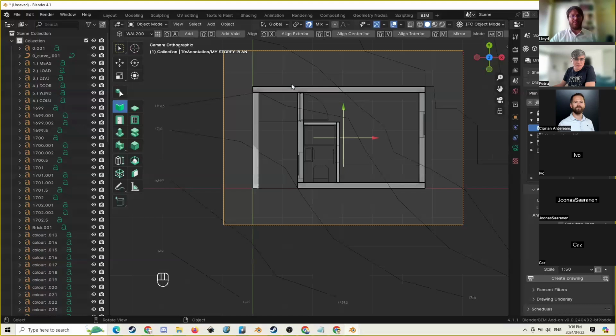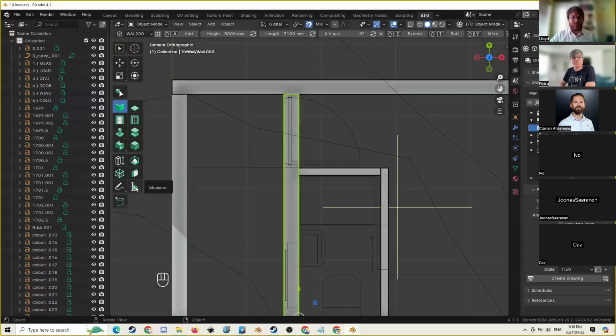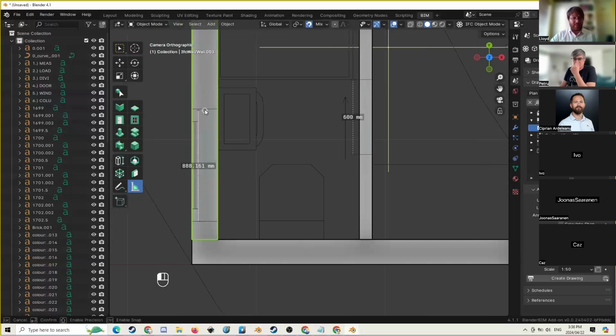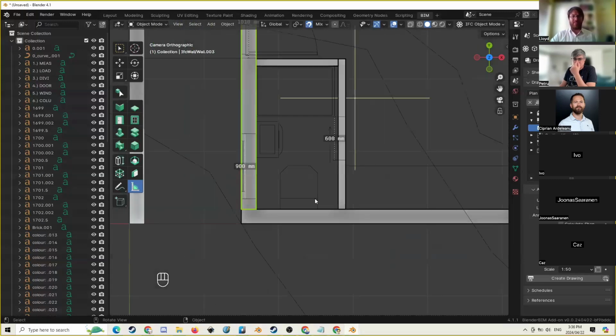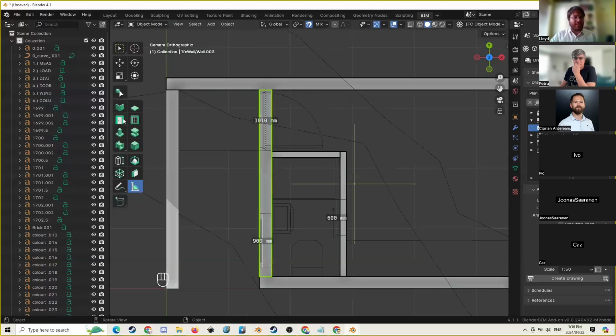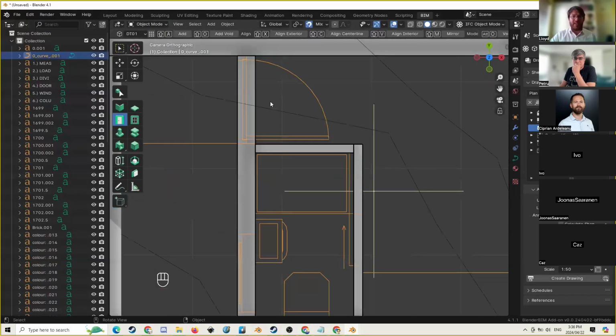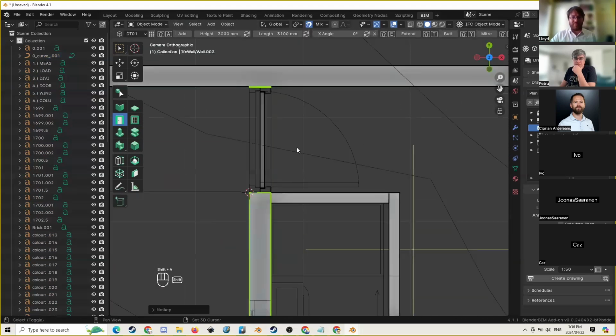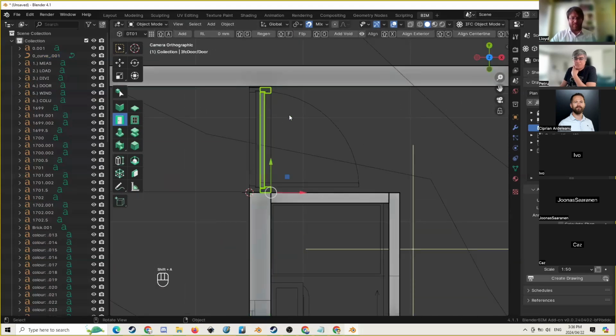Excellent. Okay, cool. The first thing we're going to do is add this drawing in. The other thing that's going to disappear is these measure marks, because they're inside of Blender, not Blender BIM. The three things we needed to measure were these doors, and the windows were the same. They were both 900. So we got those measures in again. I'm going to click the door tool and click on door type 1. Then I select this and press Shift A. So we've got our door there.